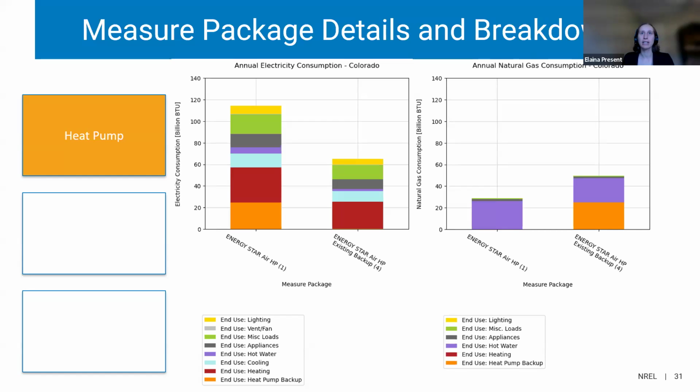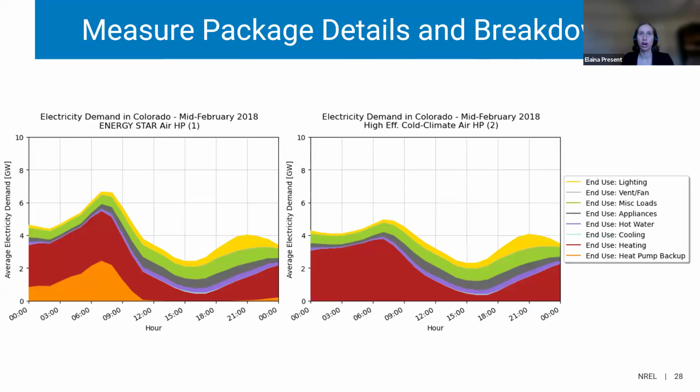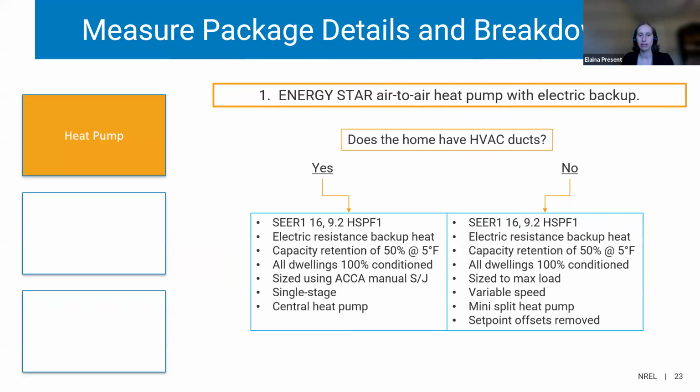This is worded strangely, but I think what they're asking is, did you model a heat pump which is not a cold climate heat pump which would have existing and has existing electric resistance backup? For example, existing electrical heating, I assume, with a new heat pump with compressor lockout between 32 and 40 Fahrenheit. Mm. So this is a non-cold climate rated heat pump, this number one. Now, what I do not think it has is compressor lockouts at that high of a temperature. I think its compressor lockout is pretty low. I think our default is like -20.